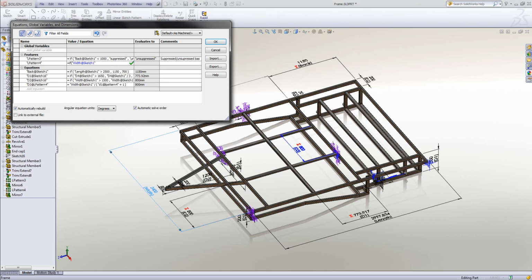that's this one. If that item goes below a certain value, so actually I'm going to do it, it's greater than 1500 actually. I want this item to be unsuppressed. Otherwise, I want it to be suppressed. Okay, close my brackets to finish the equation and hit the tick.